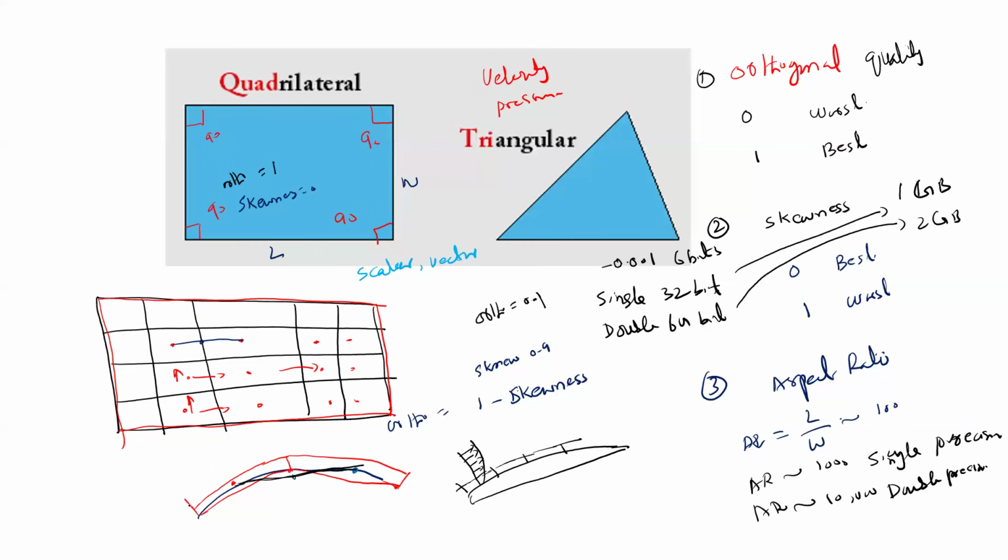So now the solution is that either we have to increase the cell size, like height this way, or we have to increase the lengthwise or the streamwise cells more there. So if you add more height here, then definitely the aspect ratio will increase. Or if you add more cells here, aspect ratio will also increase. Okay. So all these things will lead to a better quality solution and a better quality mesh. So aspect ratio should be kept in some limit, like in free flow, meaning not modular, it should be not more than 100. And in the modular, we can go up to 1000.